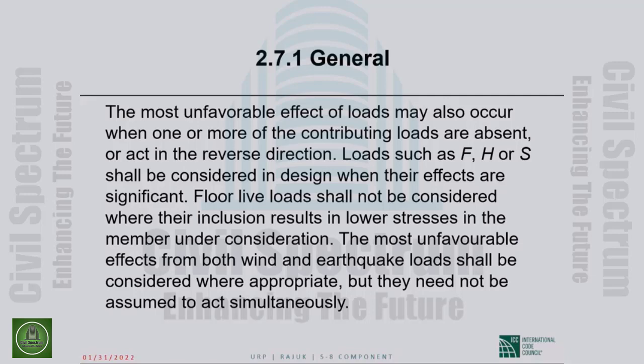Okay, so it goes on. This all makes a lot of sense. Loads such as F, H, or S. F is the fluid pressure, H is horizontal earth pressure, S is snow, shall be considered in design when their effects are significant, not otherwise.